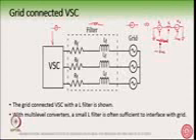Now why do we need the X? First of all, we want to control the power flow between V1 and V2, that is, between the voltage source converter and the grid. That's why an interfacing inductor X is needed in between.